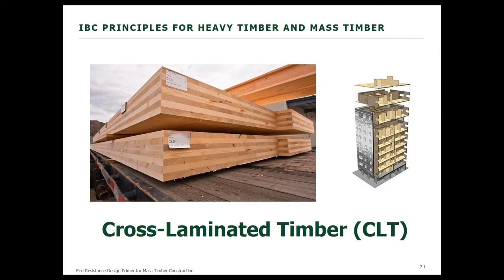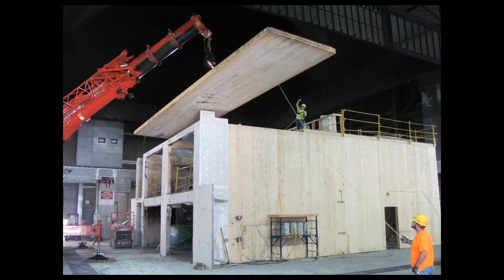Typically, what you'll see there is a 7-ply panel that's about 9 5/8 inches thick. A 3-ply panel is about 4 1/8 inches thick, and a 5-ply panel is about 6 7/8 inches thick. Here's that view of the model structure being corrected, just to basically give you one last look at the size of these mass timber CLT products.